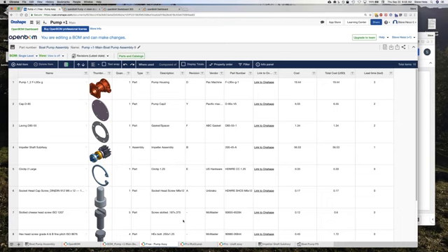It's suffice to say, in the interest of time here, that it works almost identical to inserting the Onshape BOM. In the insert dialog, you just navigate to BOM app data versus Onshape data, and choose the tab that you want to insert.